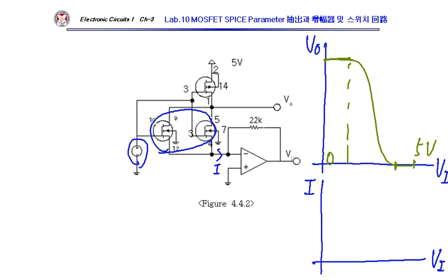Okay. So this is the NMOS threshold voltage, which may be around 1.5 or something. This is 5 minus the PMOS threshold voltage. PMOS threshold voltage is negative, right? Maybe minus 1.5, something like that. Yeah, in this region, the NMOS transistor is turned off. You can follow like that. So here's the current characteristic. You can watch a similar thing.